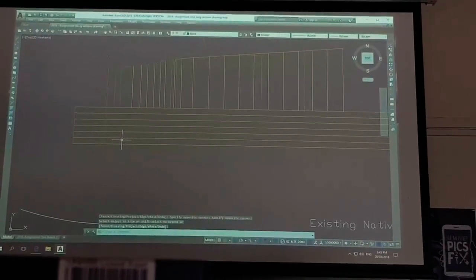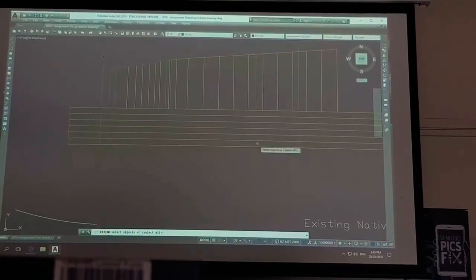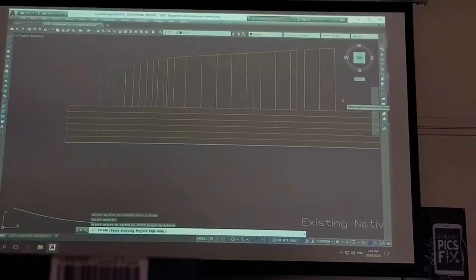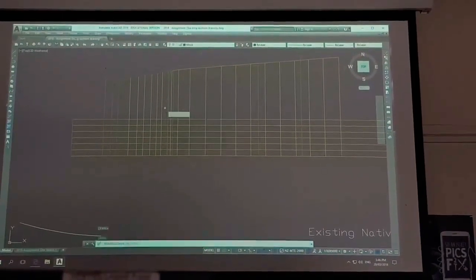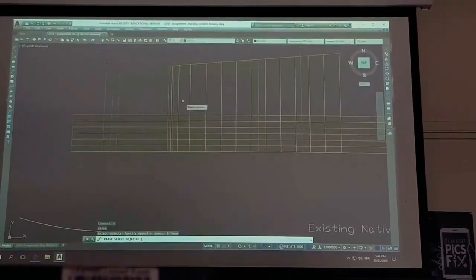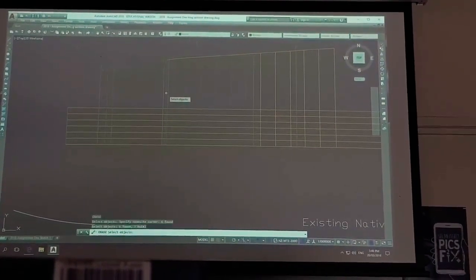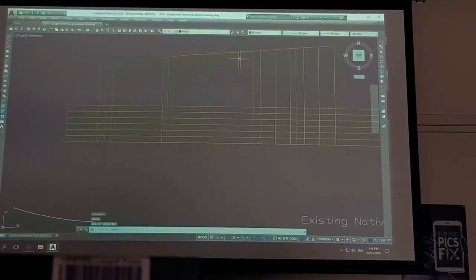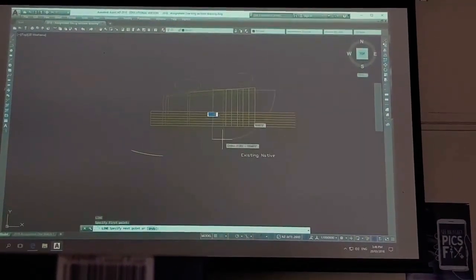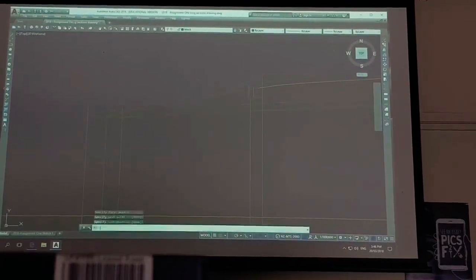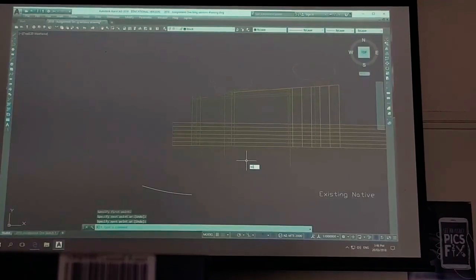And I'll extend, you remember the extend command as Ingrid showed you was over here. You click on the bottom line and do a green window through all that, look at that, extend it, okay? But you don't have to do that many lines. In fact, you don't even have to do every 5. What I would like to see is the lines coming down from the platform and the line coming down here from the platform which meets the ground, so they're important lines.